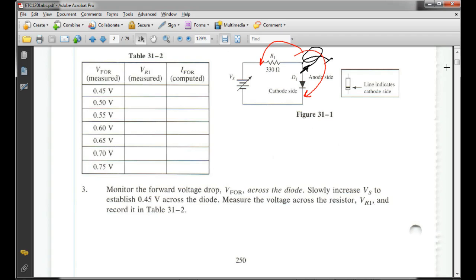So that black lead on your meter has nothing to do with the circuit ground or circuit current. It's only if you connect it to the circuit. You can put that meter anywhere in the circuit you want to, right? You understand? So back in DC, we had like two resistors, and people would measure across that one, move their meter, and measure across that one. But if you put your common right there, then all you have to do is go there, and then go there, and you're through. You wouldn't even have to move your meter leads. It's just that one of them is going to measure the opposite polarity than what's actually there.